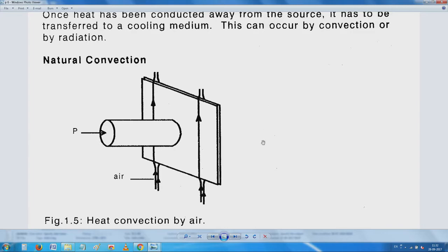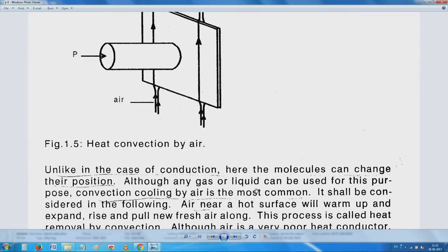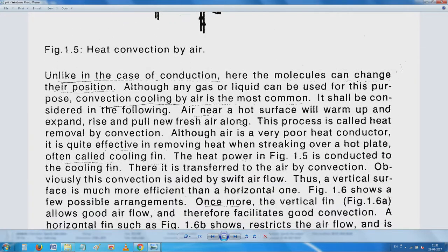By definition, convection depends heavily on position change. Understood, no? The molecules change their position. That is why heat and mass transfer are related somehow. And then, as if things are not good or bad enough, the moment you heat some portions of a fluid, it expands and buoyancy is created. That is what creates natural convection cycles or thermal cycles inside.